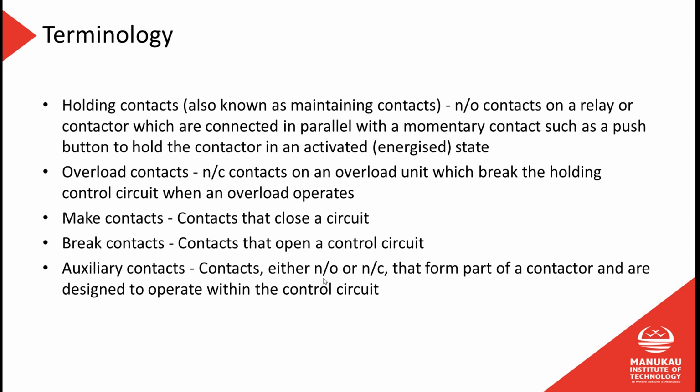Holding contacts, also known as maintaining contacts. Also, I would say we would use the terminology latching contact. This won't make much sense until one day we actually get into a classroom and play with some contactors. But this is used to hold a contactor on when we use push buttons.